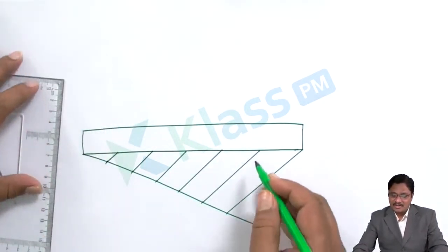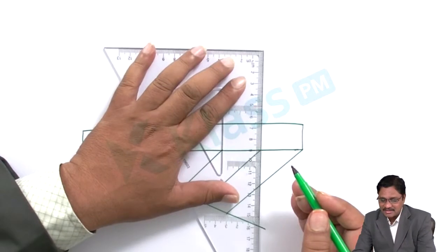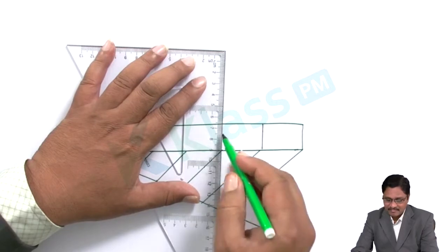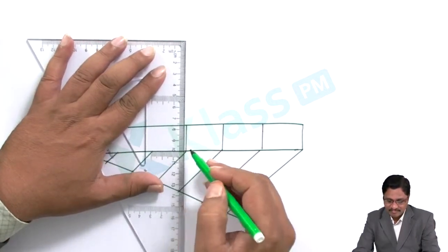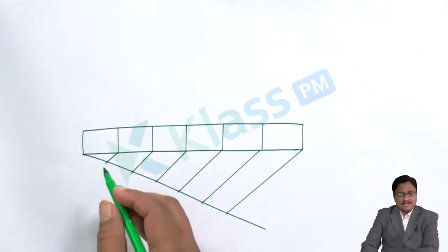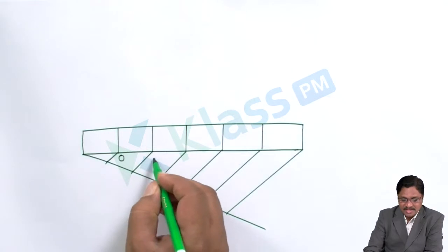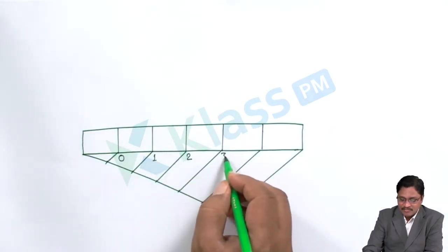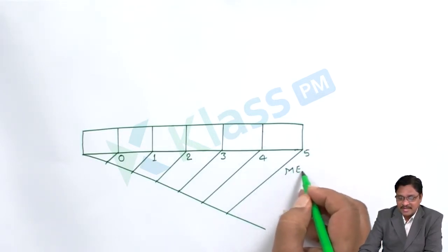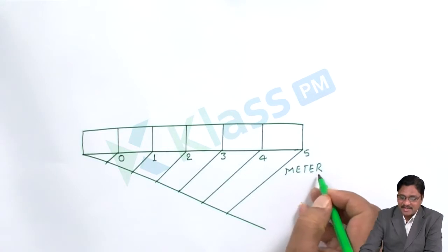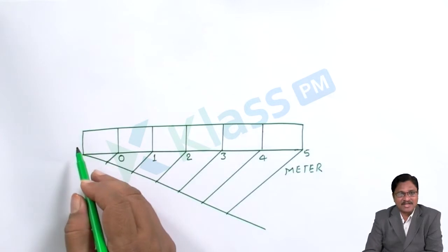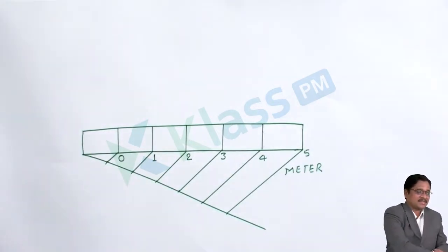Okay. Now from the points you get, draw vertical lines so that they represent the divided portions. The first one you have to leave, mark it as 0, thereafter 1, 2, 3, 4, 5. Please don't forget to write the units of measure; since we are considering meters, write meters. Same as the plain scale, the left rectangle block has to be subdivided into the required sub-level components.